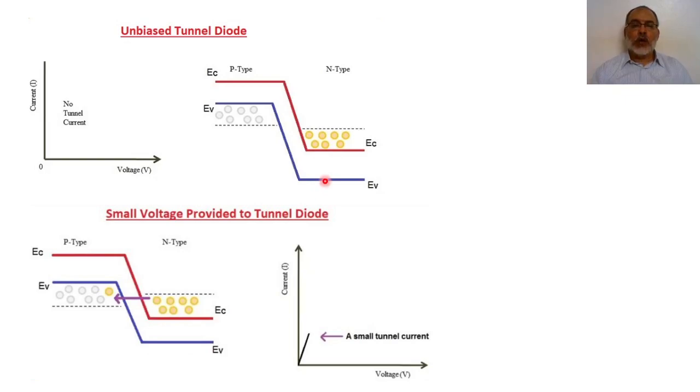On the other hand, the energy bands for the N+ type are much lower than the Fermi level. Now, if we are going to apply forward bias for such a PN junction, so we are applying negative here and positive here. In this case, the negative voltage at the side of the N type will push the electrons in this direction, away from the negative.